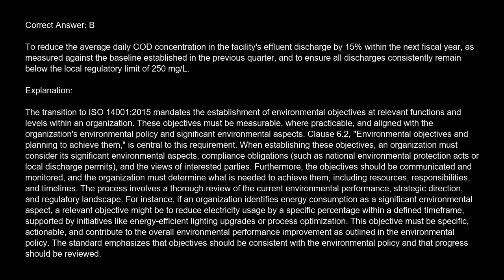Correct answer is B. To reduce the average daily COD concentration in the facility's effluent discharge by 15% within the next fiscal year, as measured against the baseline established in the previous quarter, and to ensure all discharges consistently remain below the local regulatory limit of 250 mg/L.